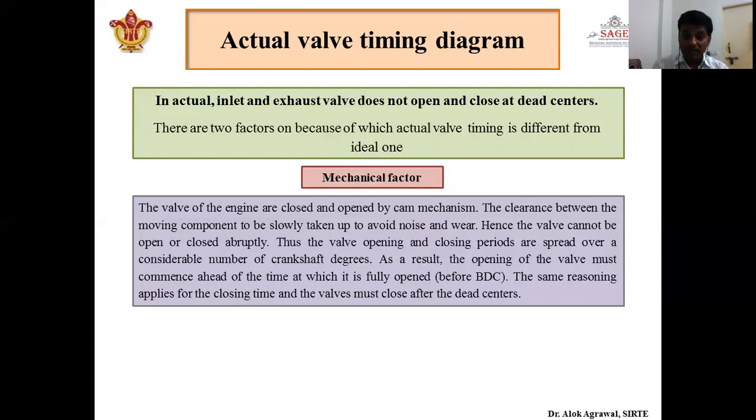Otherwise, what will happen at the time of the suction stroke, when the piston moves from top dead center to bottom dead center? It may be possible that the valve is not open properly, and because of that, a lesser amount of air and fuel mixture will be inducted into the chamber. So because of this mechanical factor, we have to make the valve open well before top dead center.